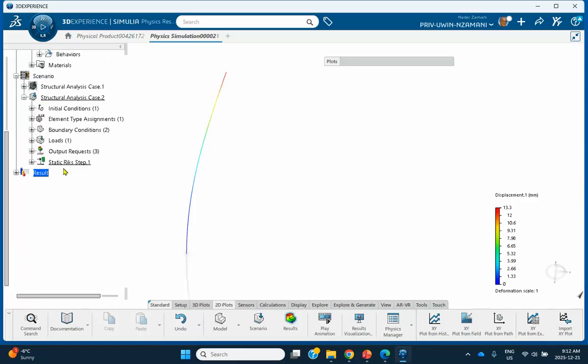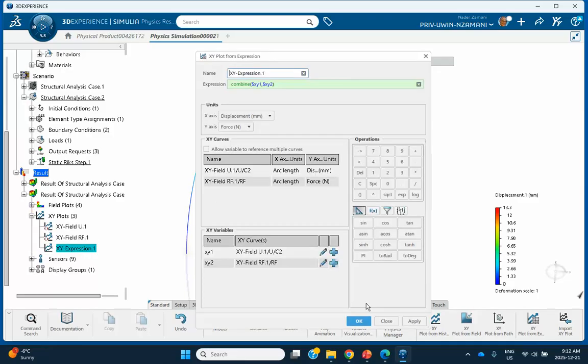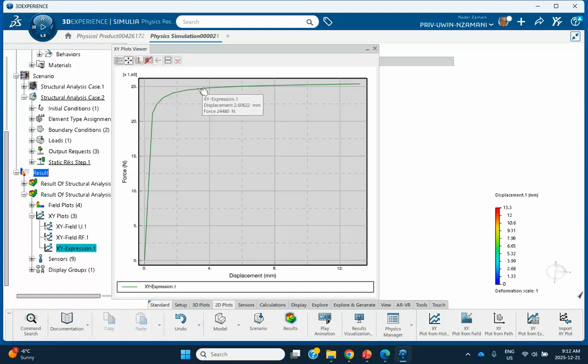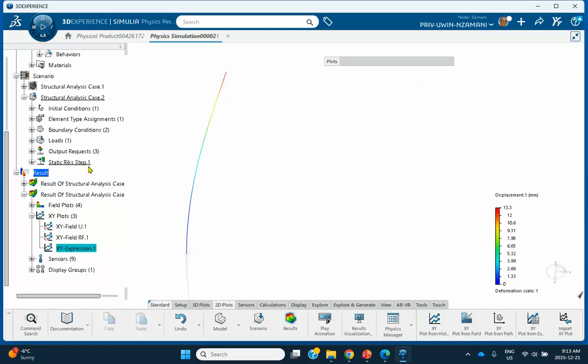Okay. Right now, for zero imperfection, let me go back here for a second. Result, I'll show you something. For zero imperfection, this is a bifurcation problem. It goes to 25,000 and then horizontally. The smaller the imperfection, the closer it's going to be to that jump. But if you increase the imperfection, it's going to become more gradual.